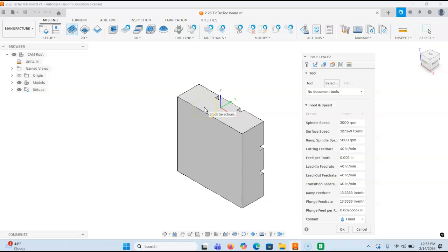Now, you guys probably know by now these type of facing cutters are generally some type of an end mill or an inserted cutter. Large shell mills, again, when we're facing, we generally want to select the largest tool that we can so that we can minimize the number of passes that we have to take. Facing is usually performed with a flat end mill or facing tool, and we try to keep the largest diameter so that we can minimize the number of passes.